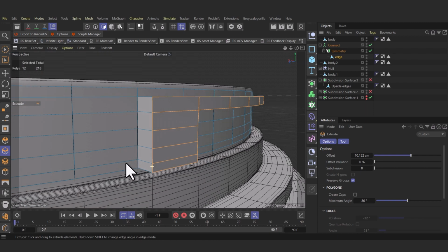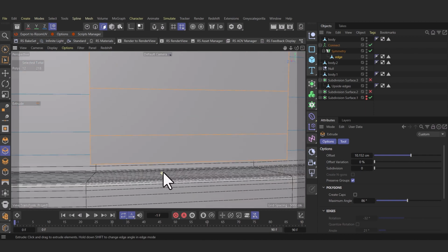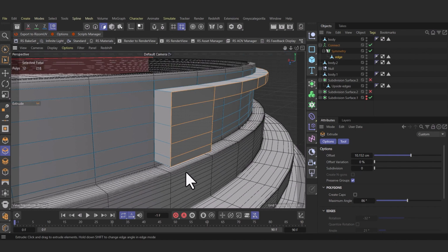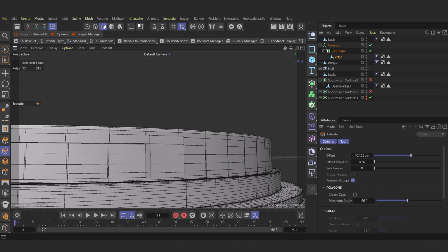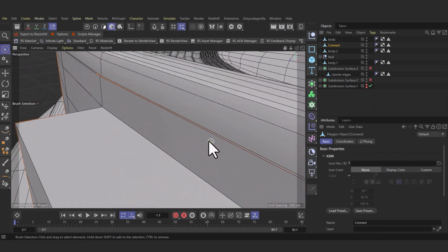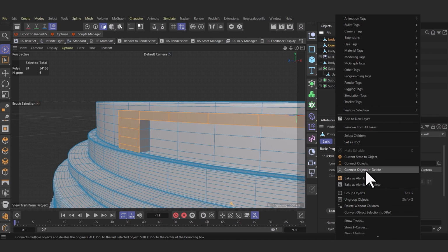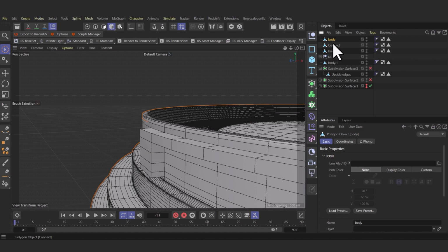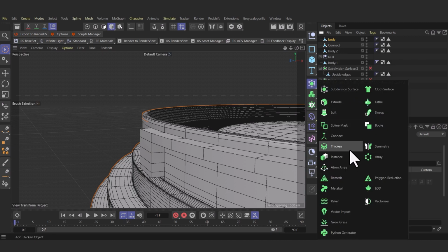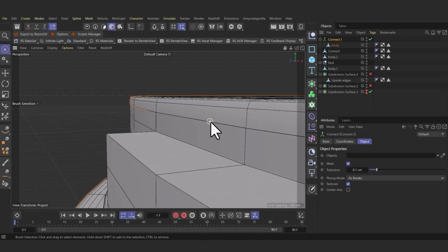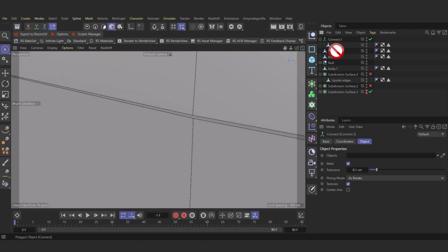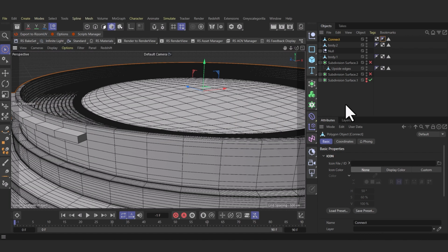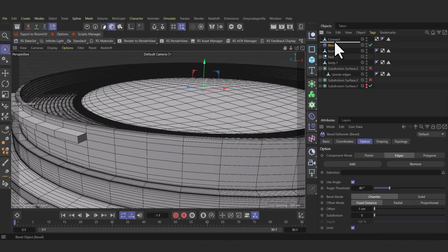So now I have two appendages that have formed on both sides of the circle, one on this side, one on that side. If you remember, I had separated this area and worked on it as a separate layer. Now I want to reattach it to the main body of the lens. Well, I put both layers very easily under a connect generator. Then, by pressing the C key on the generator, I turn everything into one layer.